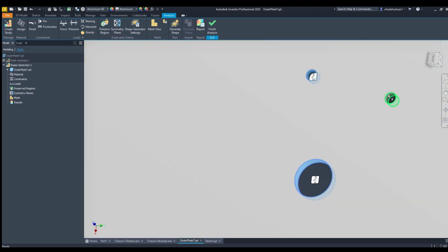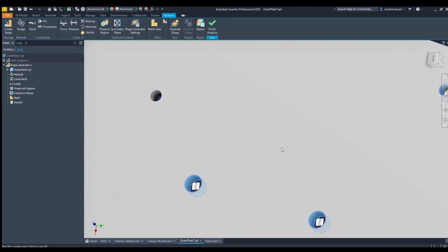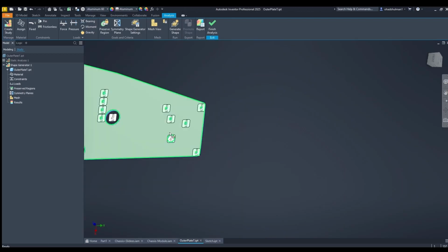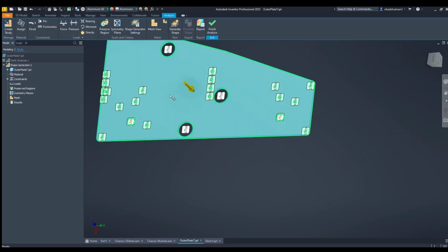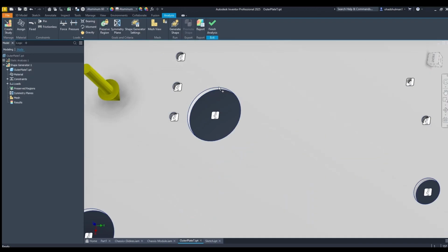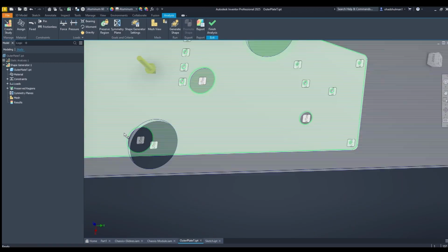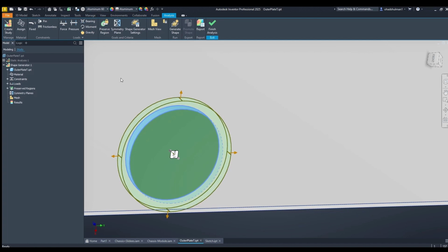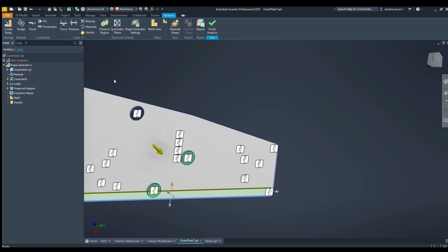Now, one key difference here is that the fixed areas in this aren't actually any place that is bolted into place. It's any part that has anything connected to it. So I applied the fixed constraint to all of my different holes. Now I'll apply a force, the same force, 1000 newtons, and preserve region. This is the important one. You basically create these green areas and tell it to not change those areas.